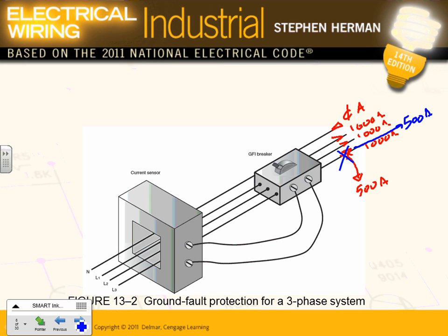Can you guys see now the system is unbalanced? If you do the math, there will be an I neutral current going here because it's substantially unbalanced, right? And this device, the CT, will look. The minute it sees something like this, it will create a 5 amp current that goes to a little coil here, and that little coil energizes and bam, trips the circuit breaker.